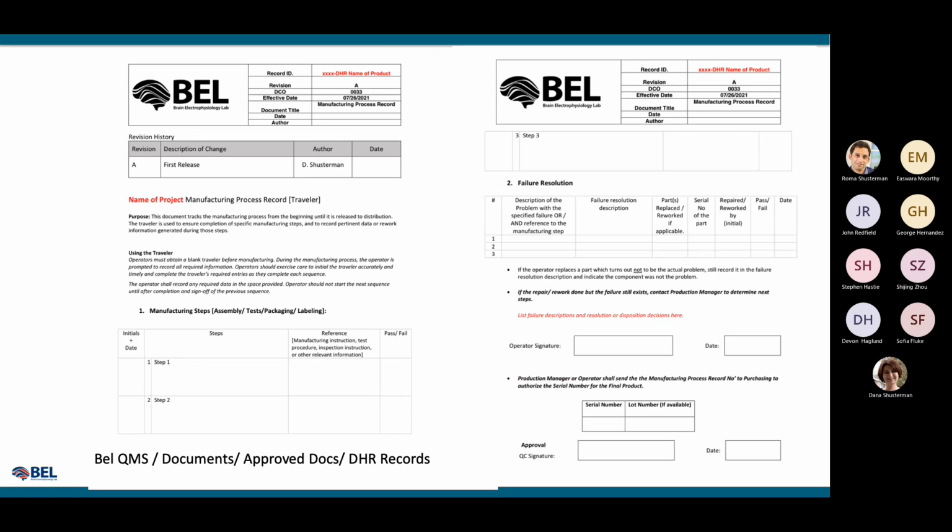The assembly process is a monitored process. The production operator should document and evaluate every step of the process, where every step should have a reference to the specific assembly instruction that we mentioned before and its acceptance status. This process is the assurance that the production was done properly. In case problems with procedures and instructions are discovered, they should be mentioned, fixed, and reapproved before we start the next production unit.